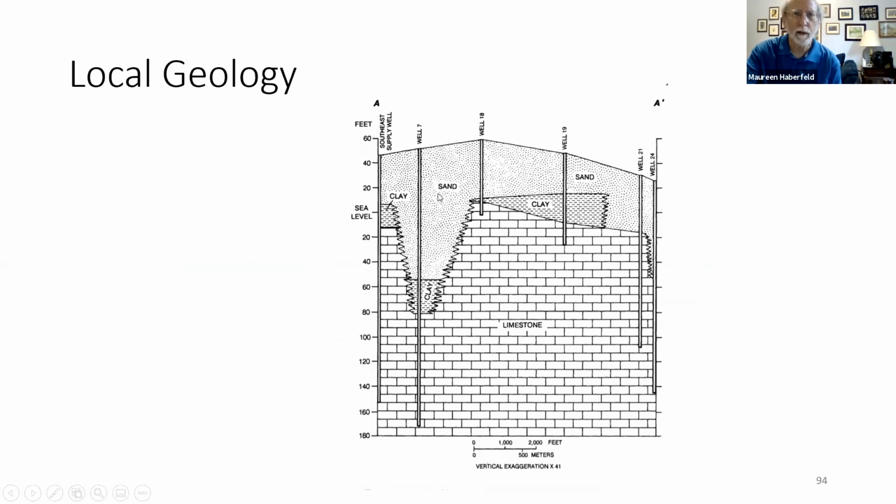It goes through a thin layer of sand and into the limestone. On the left, you can see how deep the sand and the limestone are. Between a depth of 20 feet and 80 feet, you're in limestone, and that's the Floridan aquifer. So all the water that is coming from the city and being irrigated, what isn't taken up by the crops or evaporating, is going into the Floridan aquifer.